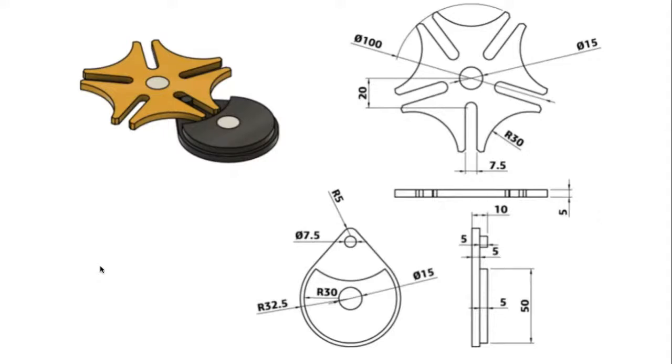And these construction models are very useful because when we are working with some extraordinary projects or very large assemblies, these construction entities can't be differentiated if we do not make them hidden line or something, and it will cause confusion. So this feature of converting construction lines into dotted entities is very useful in Fusion 360.